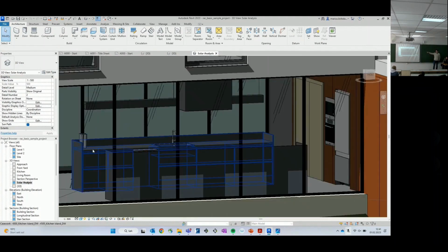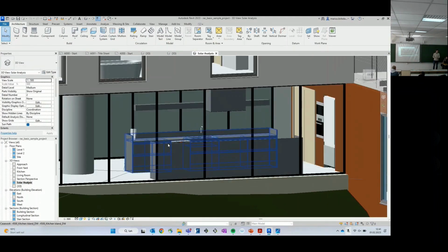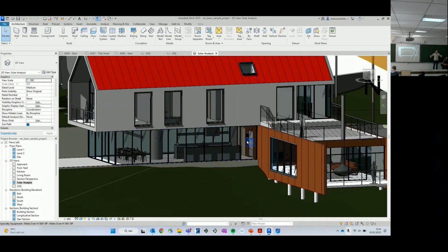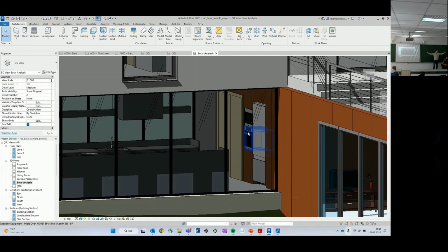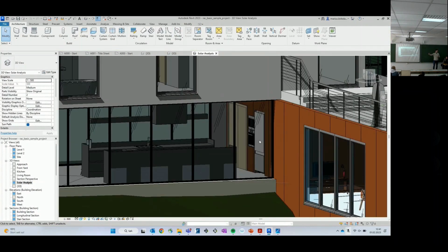No. For instance, for a slab like that, if it's 4x4 or 100 by 100 or 100 by 50 or something, it will take the same amount of time to model the reinforcement and give it precise information. Because of the tools available in Revit, you can automatically distribute the reinforcement in the spacing that you choose.